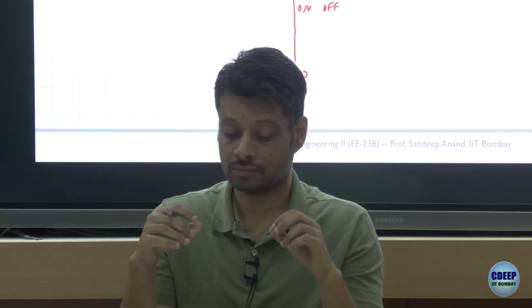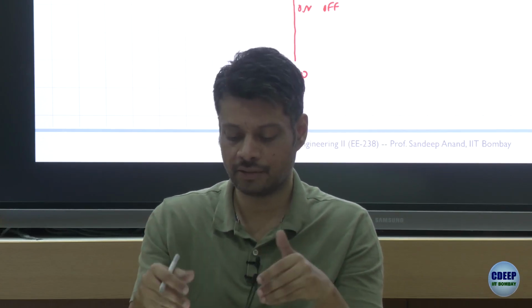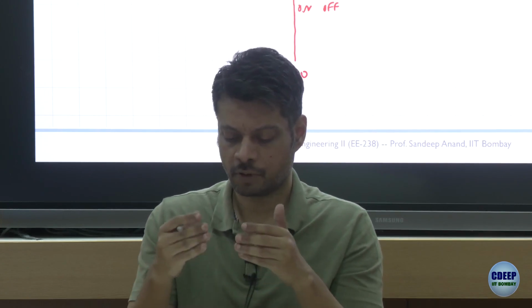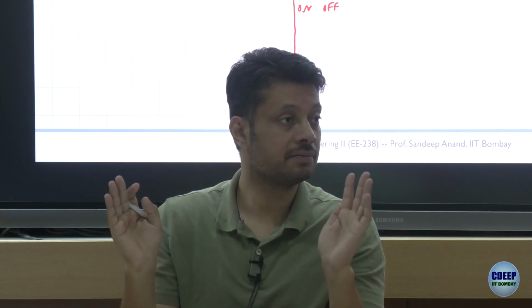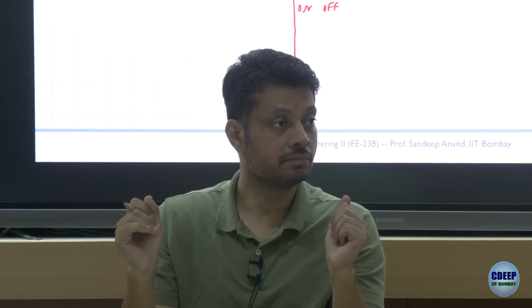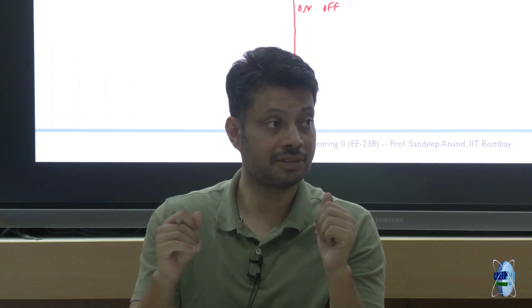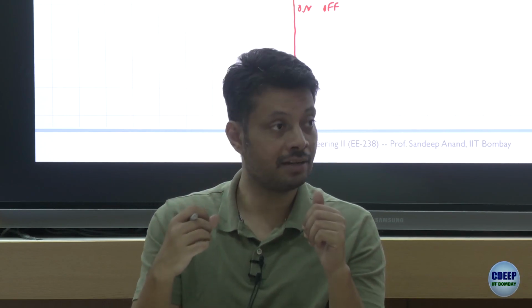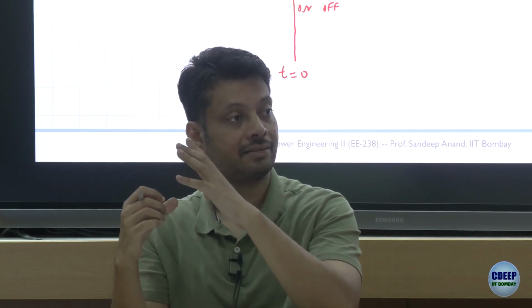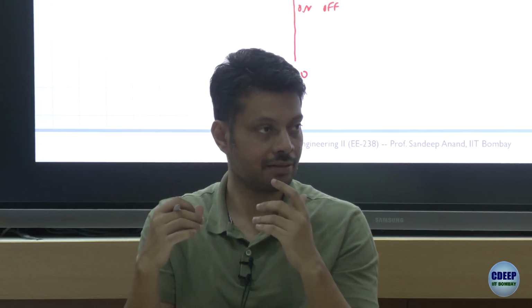The slope is negative at the start and also later; from pi by 2 to pi, the slope is always negative. It will never be able to cut, because as soon as the output voltage goes below it, your input will charge it. So it will never cross it.